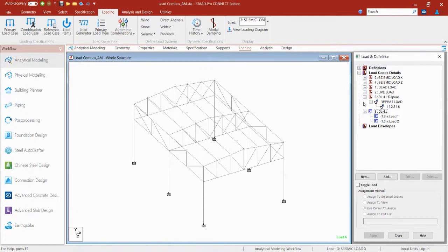Now, just as a reminder, I'll probably mention this several times, but this is treated as a new primary load, and a second order analysis, such as a P delta analysis, will reflect the correct second order effects when using a repeat load case. Now, of course, we all know, and again, this is probably quite review for my experienced users in here, but we all know that creating a manual load combination could be tedious, especially if you have multiple load cases within your model.